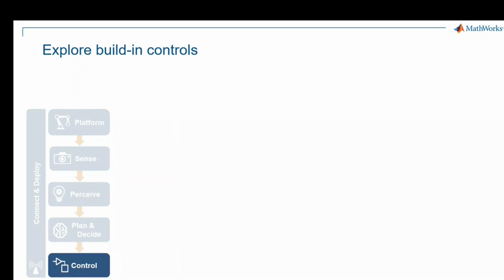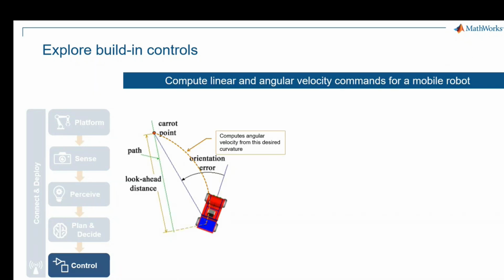The first I would like to go over quickly today is the Pure Pursuit controller, which is one of the most classic ones. The idea of this controller is that you can define your desired linear velocity, angular velocity, and look-ahead distance. And given the set of waypoints that were defined by your path planner, the controller will guide the robot along these waypoints.